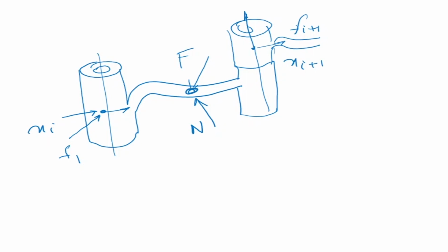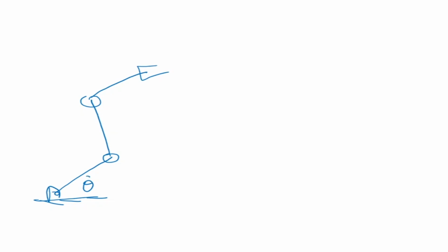Before we go to the equations, let's try to understand this a little more clearly. This is my linkage. There is a velocity here, theta 1 dot, theta 2 dot, like that. This will cause a velocity on that side, as we have seen, and it is going to propagate in the forward direction. These velocities and accelerations will cause a force to act on the CG of the links. This is the CG of the links. Because there is a force acting on the CG, this force will come backwards and get reflected onto the joint torques. So there are two loops. This process is iterative.